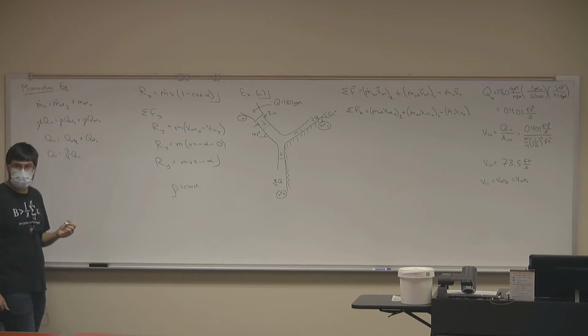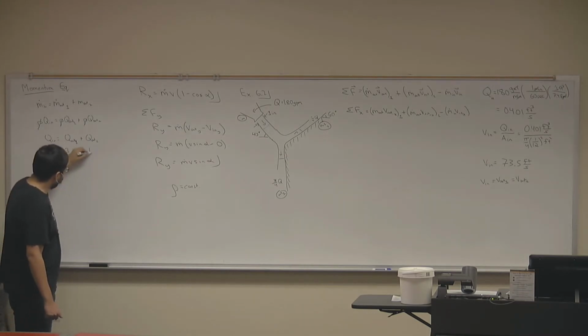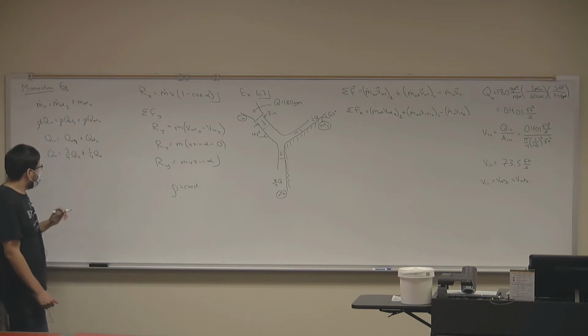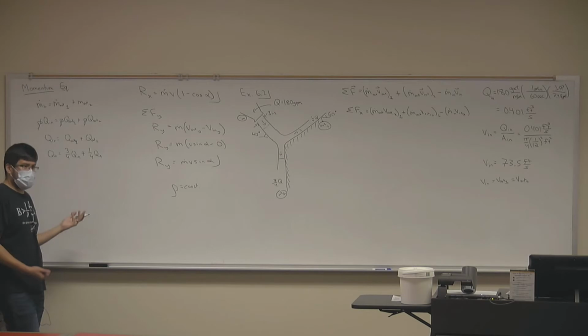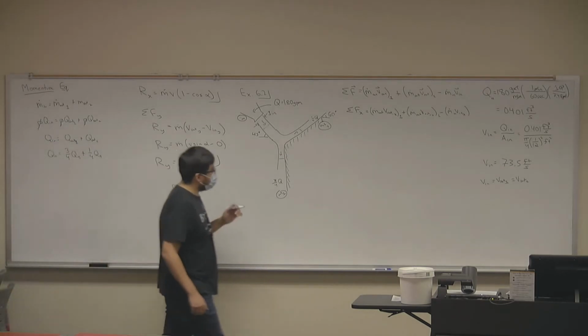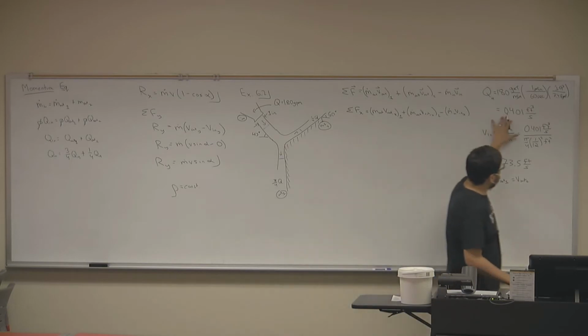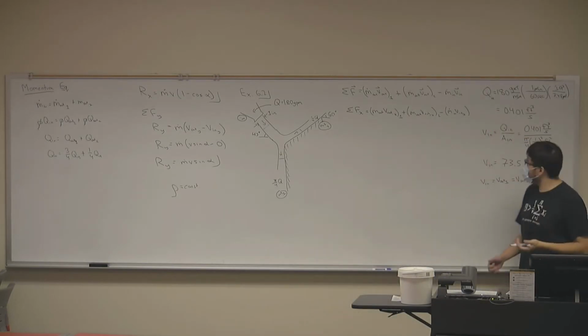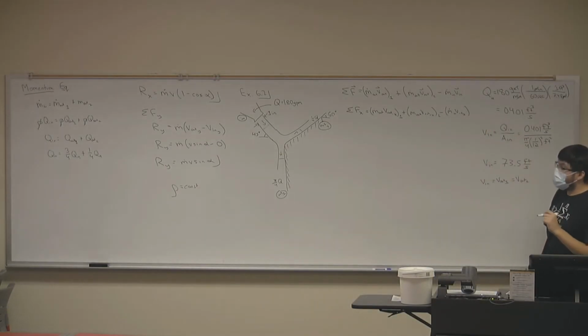And then flow rate out 2 is equal to 1/4 of flow rate in. Add these up, you get 4/4 flow rate in, and just flow rate in equals flow rate in. So what I want to get at with this is that as long as you know the flow rate and the distribution, you should be able to calculate all your other flow rates.